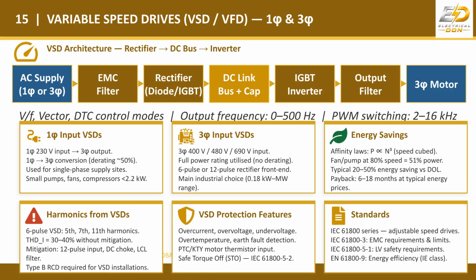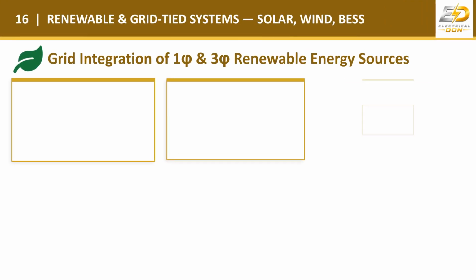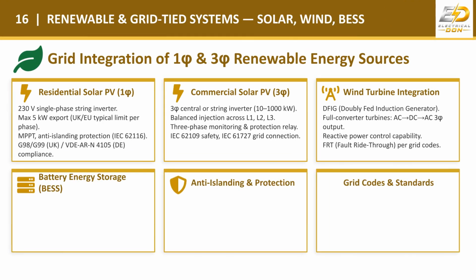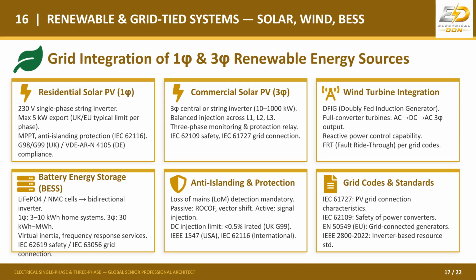Single-phase input VSDs are used for smaller loads, while three-phase VSDs are standard for industrial applications, offering significant energy savings and various protection features. Renewable energy integration involves residential and commercial solar PV, wind turbines, and battery energy storage systems. All installations require anti-islanding protection and compliance with various grid codes and standards, such as IEC 61727 and IEEE 1547.